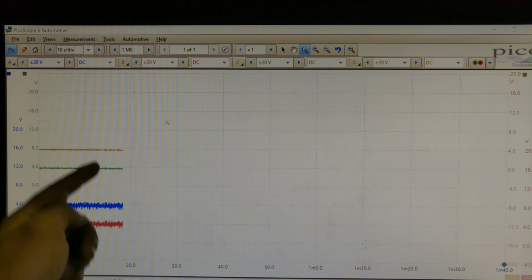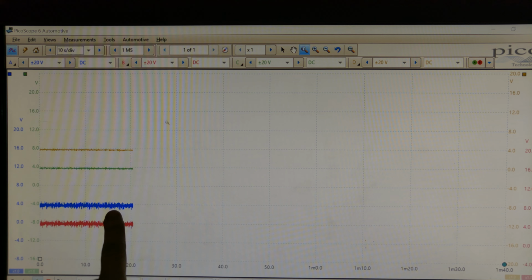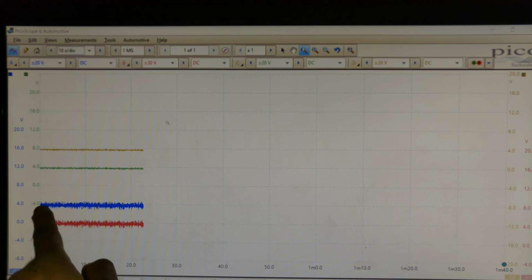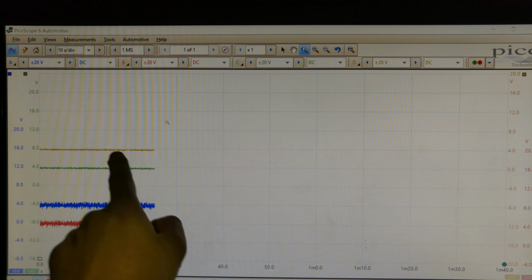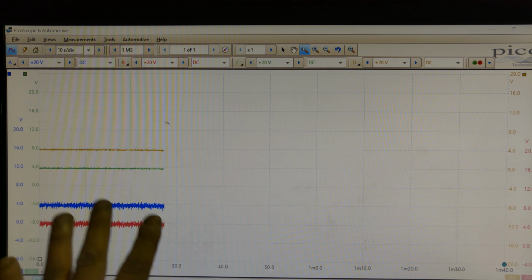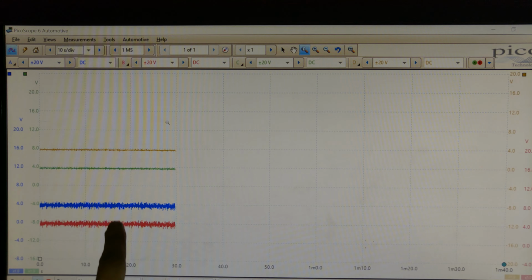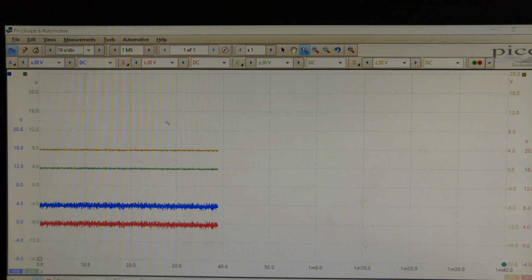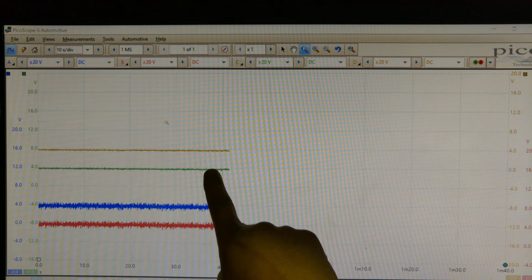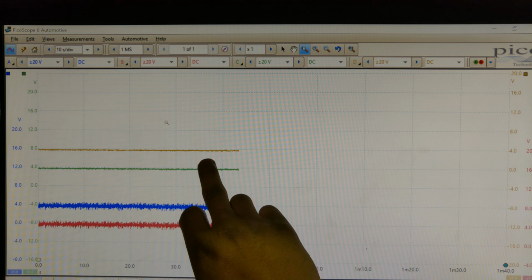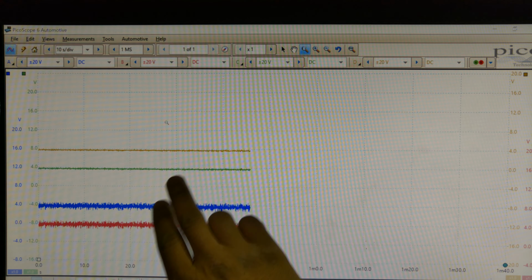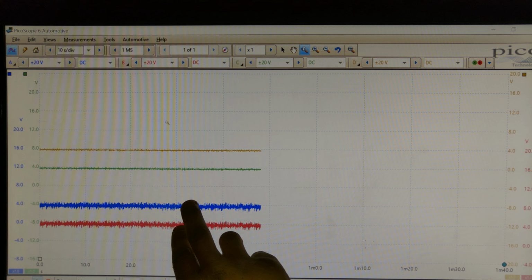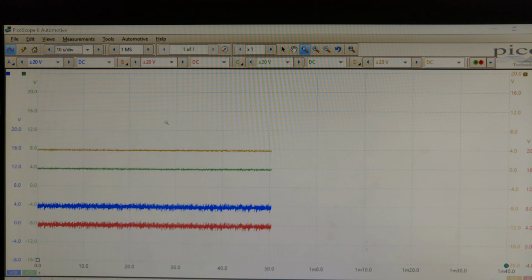We're looking at a little bit different picture, like this is a bit dirty, 4 volts compared to that. That's much cleaner. I think it's because of my ground point, I'm just getting the ground off the block, so just ignore that completely. I'm going to change gears now and see which one moves, what happens. So just remember this top 2 here is for the top clutch actuator. This bottom is for the bottom actuator. That's how I've got my setup there.